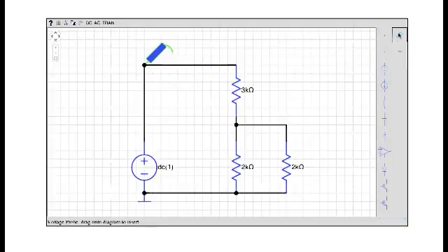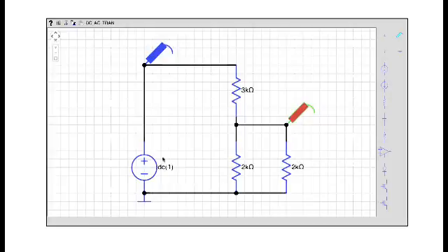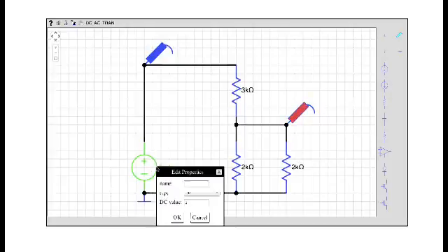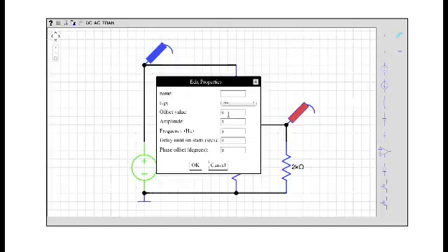And then for the output of the battery, and then for the middle node of the voltage divider, let's make that a red waveform. And just so we have something interesting to see, I would like to change my voltage source to a sinusoidal voltage source. So it's plus and minus 1 volts around the 0 volt center line, which is just fine. I'm going to ask for 100 hertz